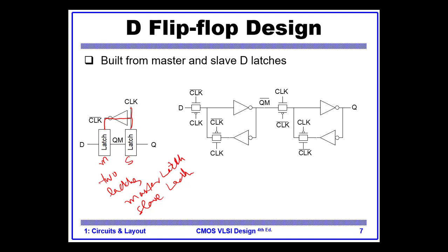Because of the clock signal and how it is connected to the master and slave, with a NOT gate, there is no point in time at which both the latches are transparent.